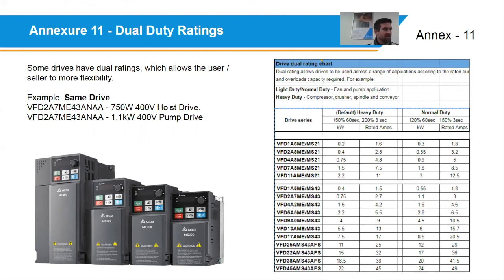In ISP soft, you could easily have data tables set up to read multiple drives. If you're looking at from the drive's perspective, you would use VFD soft to set up parameters or just the keypad. And from the SCADA side, you would use the DIA view software.